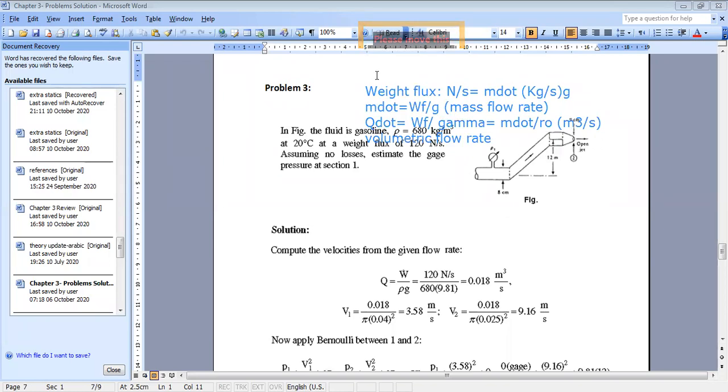And whenever you have a flow between two locations, and all conditions for Bernoulli equations are here because we have steady, incompressible flow, we can neglect viscous effect. If you have the flow in a circular tube, you will take a streamline that is far from the walls.